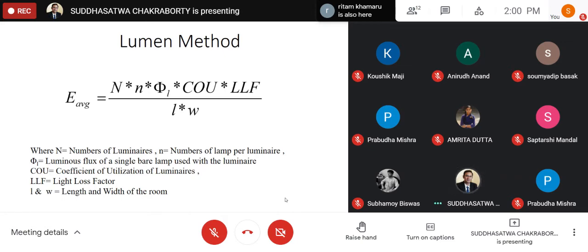300 is a case where, number one, the speed and accuracy of the job is very low. Number two, the average user's age is very young, which means you need less light. Young people need less light, and here your room is contributing more light, so the reflection from the room is higher. The maximum is required when my average room surface condition is not supporting, it's dark, so I need more light to reflect. Number one. Number two, here the average age of the user is quite high.